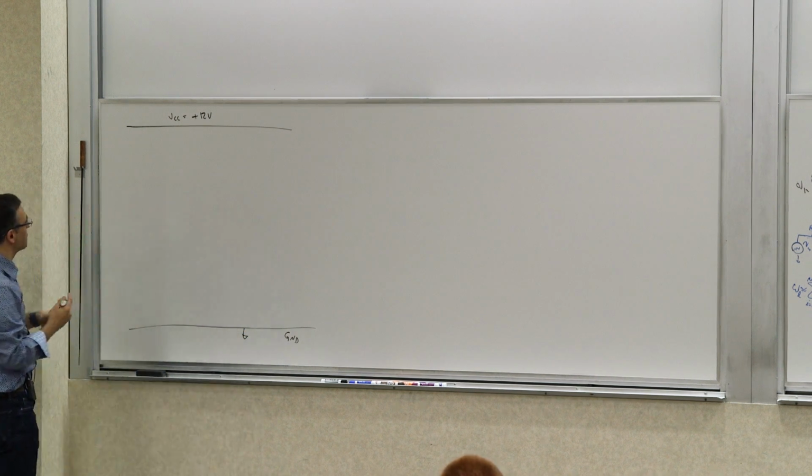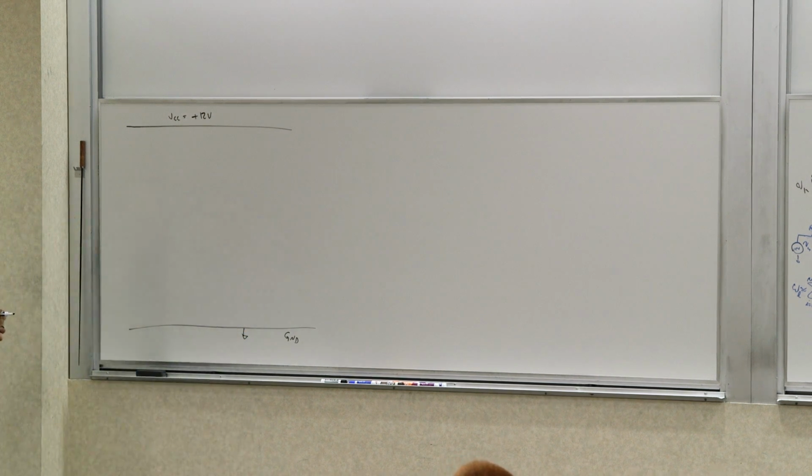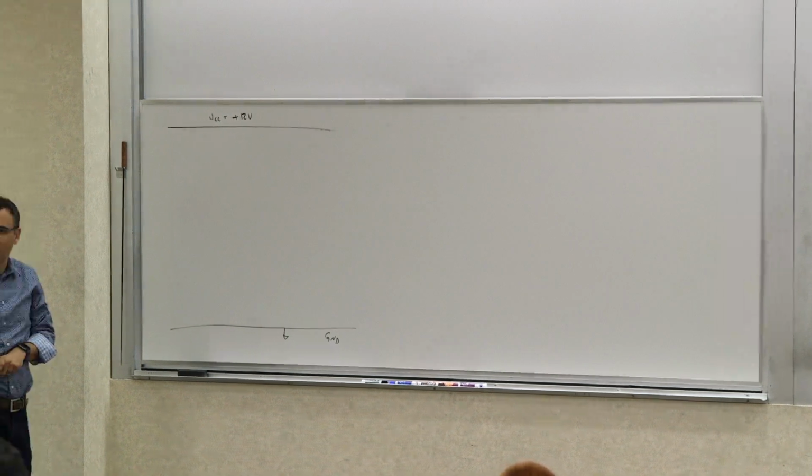And we want to make our circuit. So first we have to bias our transistors, right? So how do I bias that gain, the common emitter transistor, the one in the middle, lower transistor, right? So we have to bias it. If we just apply a voltage to its emitter, it's going to be very sensitive. We talked about this in terms of biasing.